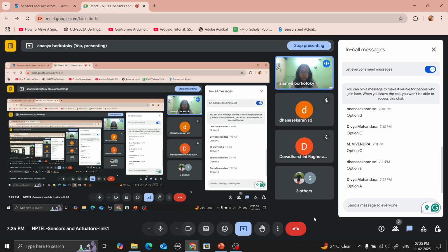Now what you normally want is that you will pattern the SiO2 layer, the sacrificial layer, and on top of it you will deposit some material. As I mentioned earlier, sometimes you want to do the deposition at a very high temperature, or some processes after making the sacrificial layer will go to a very high temperature, or there may be stress and strain on the sacrificial layer. So you want a layer which is stable for these processes. SiO2 is very stable.